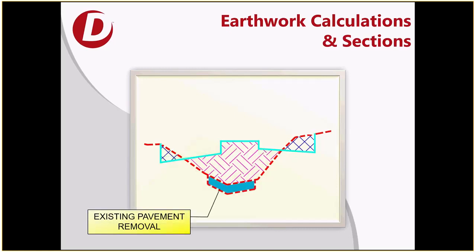Another thing that is often missed is on some projects, you have significant removals of the native or of pavements or foundations. For example, on our S1 project, we have an old building site on the project. So we're going to remove the foundations from that building, and obviously the survey went to the top of that concrete. We're going to have to manually adjust out the foundations or the slabs of the building when we build a new existing ground line.